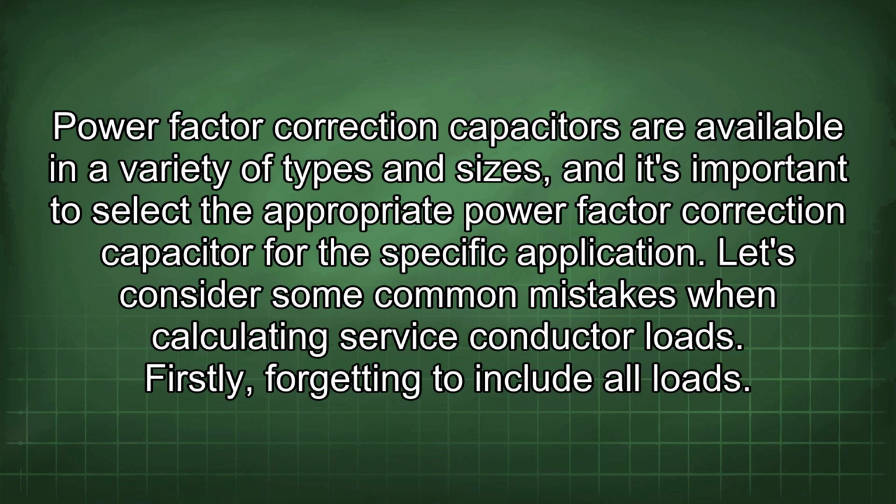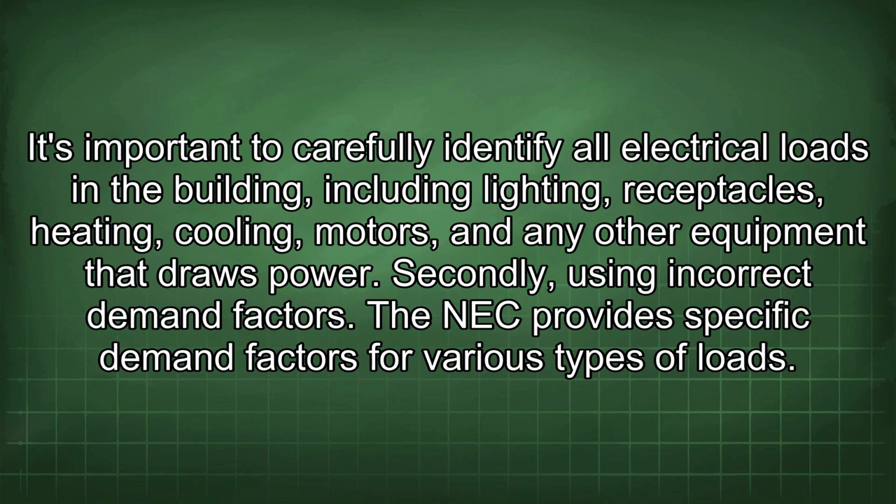Let's consider some common mistakes when calculating service conductor loads. Firstly, forgetting to include all loads. It's important to carefully identify all electrical loads in the building, including lighting, receptacles, heating, cooling, motors, and any other equipment that draws power. Secondly, using incorrect demand factors.